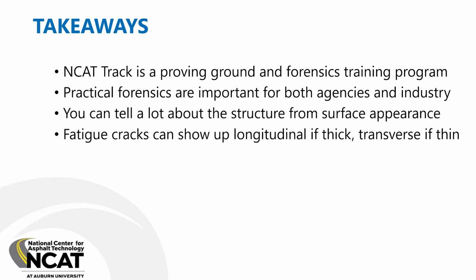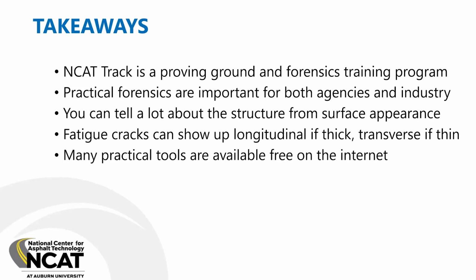So the way you see fatigue cracking is itself an indication of how much pavement thickness you have. If they're showing up longitudinal, it might be 6 inches or more, and if it's showing up in the transverse direction, it might be less than 6 inches. And that can also be indicative of debonding, if you have debonding in between layers and you have the pavement responding like a thin pavement.